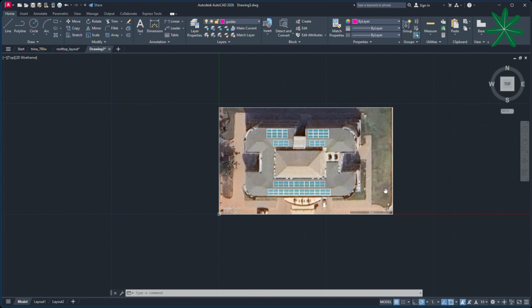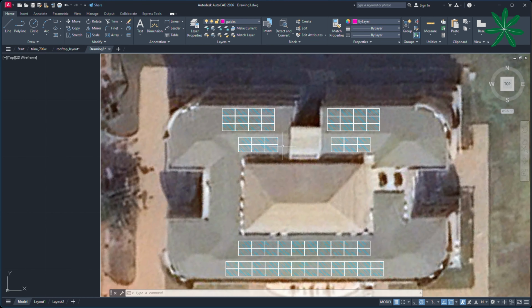Now one thing is that it's aligned towards the north, right? And we know that the sun rises from the east and sets at the west, so shadows will fall on the left side, on this side of the building. That means that shadows will never fall on this side of the building, because that is the order. It never goes in reverse. So we can shift that side closely towards the building to make more room behind there for a couple of panels to be placed. Now we are going to go on and do that.